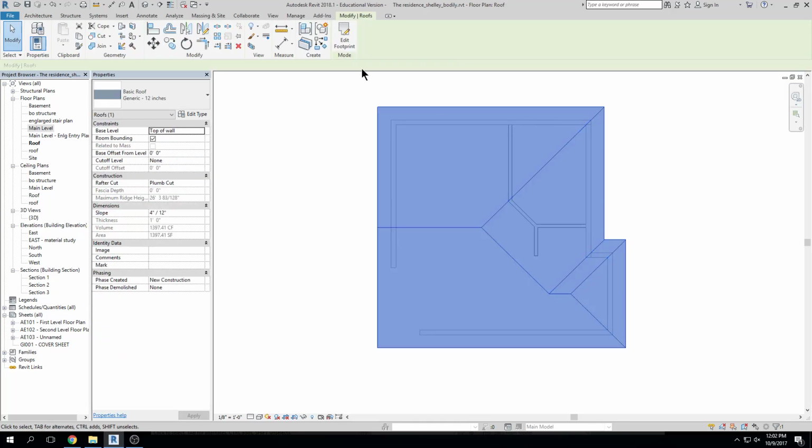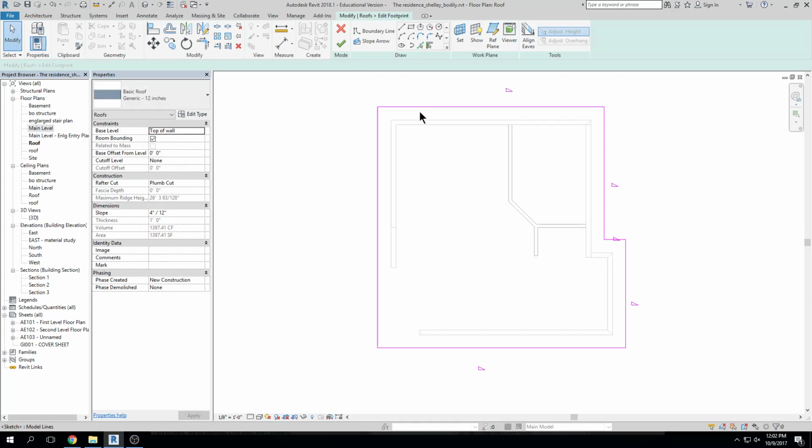Let me hit edit here. Okay. So the overhangs are not a base offset. They're not connected with a level, right? It's a drawing method. So I'm going to click on the line tool, and the offset is right here. So I could do something like 5 foot, enter, right? And so now when I click, it's going to offset it, and it's to the exterior, but if it had